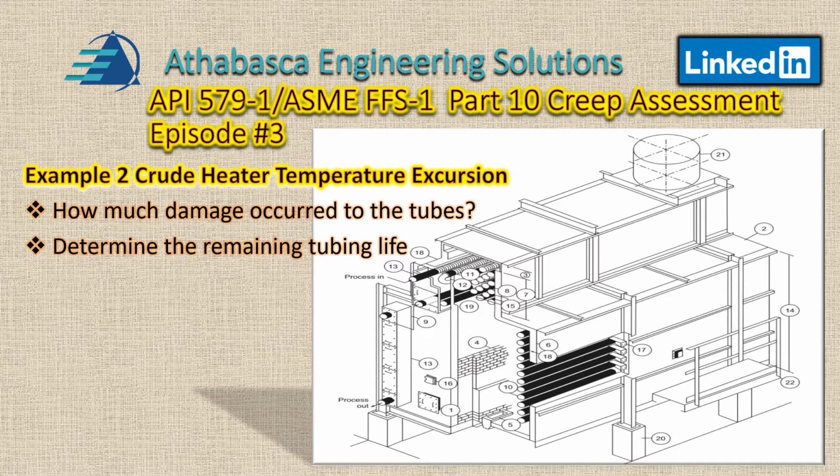The background is that the fired crude heater experienced a temperature excursion for a short duration. The refinery needs to know how much damage occurred so they can understand how the excursion impacts the remaining tube life. From this information, you can determine if the heater will need to be retubed at an upcoming scheduled turnaround, or if the tubes are likely to last even another run.